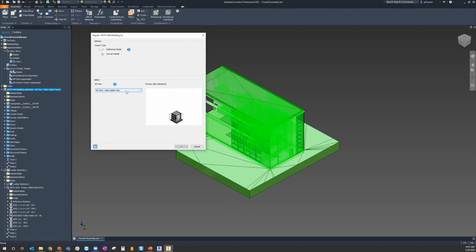But if you do an adaptable assembly, depending on where it's created, for instance, maybe I have this adaptable assembly on this portion of this building right here. If I change my 3D view to a different portion of the building that may not even include that, you may lose some of that adaptability and some of those constraints. So that's something that will end up happening.